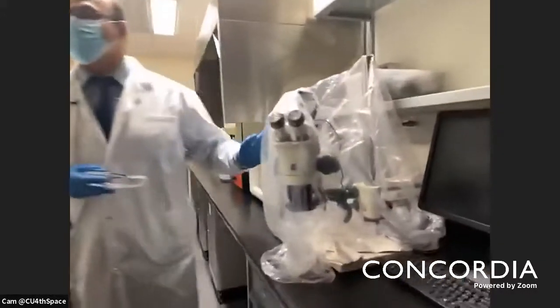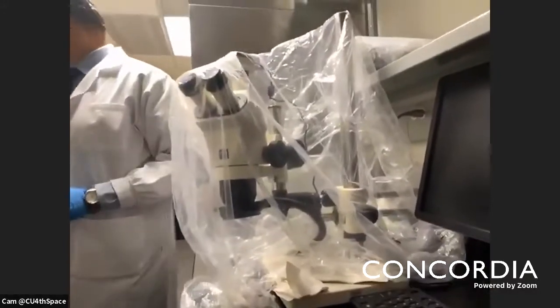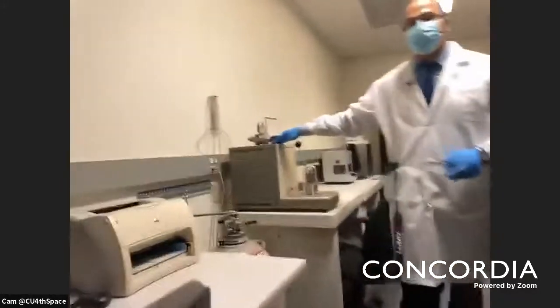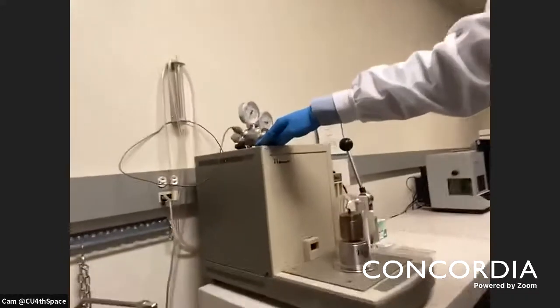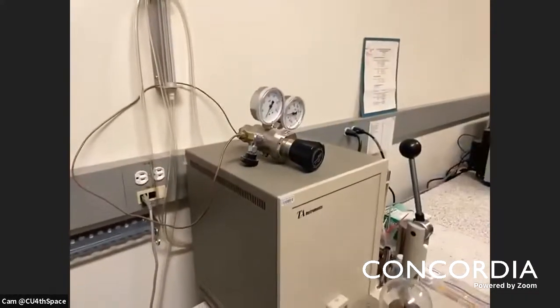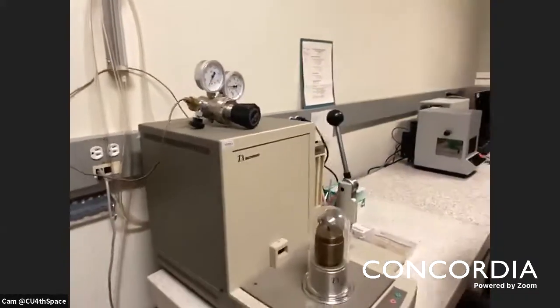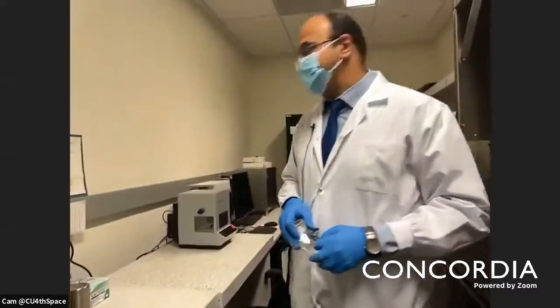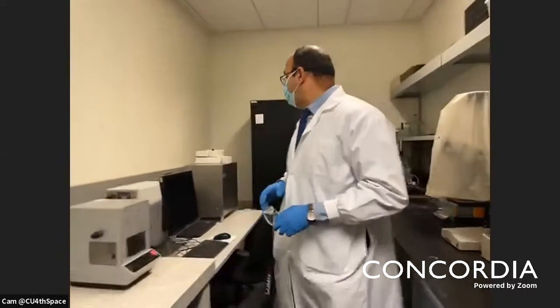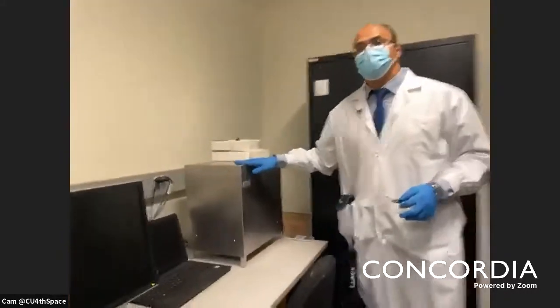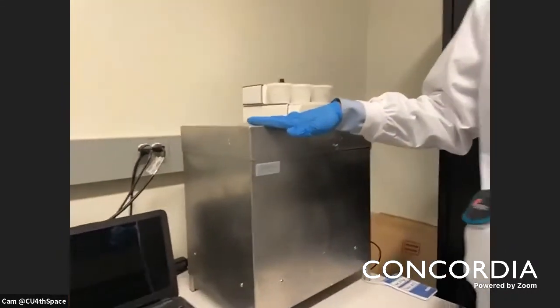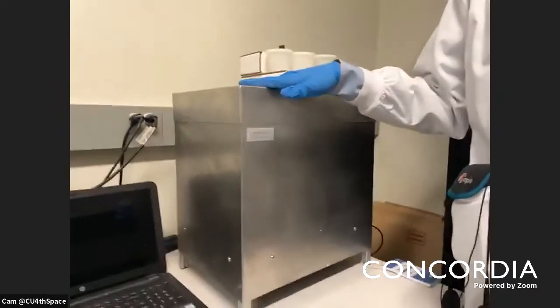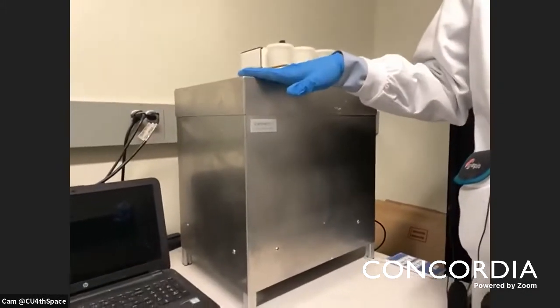We have the optical microscope if we would like to see what's happening inside our sample. We have the DSC, or differential scanning calorimetry, for thermal analysis of our sample. And this one can reach up to 1000 degrees. We are going to burn the sample to see exactly what the components in our sample are. And we have here the heat of hydration test, which measures how fast the hydration process, the chemical reaction between cement and water, occurs.